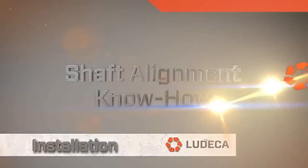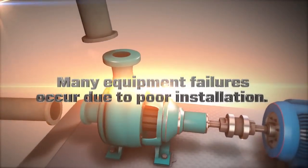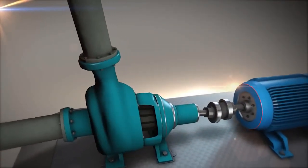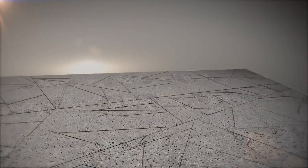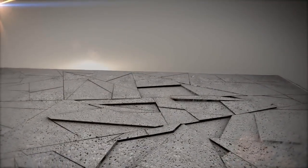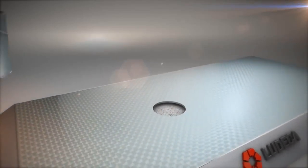Shaft alignment know-how. Installation. Many equipment failures occur during what is called the infant mortality period. In other words, soon after machines are first put in service and are typically due to poor installation. The foundation must be able to withstand the mass of the equipment and any operational load stresses and vibration that the machines will generate.